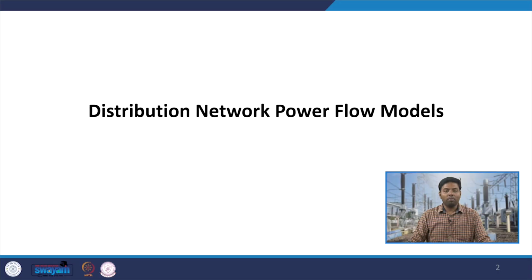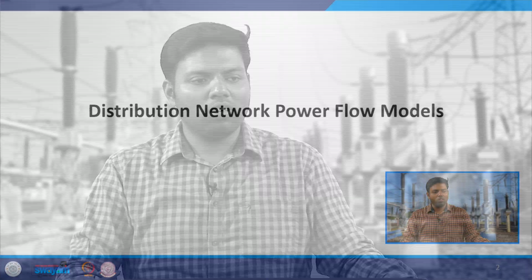We are continuing with our module 2, what is DER Integrated Distribution Network Modeling. So, till now we have seen the model of the DERs, loads, volt var controlling devices, and also the line model for distribution feeders depending upon their voltage and the current that we represented with the ABCD parameter. So, today we will start with the distribution network power flow models, which are mostly used whenever you go for optimal power flow studies or distribution network planning.